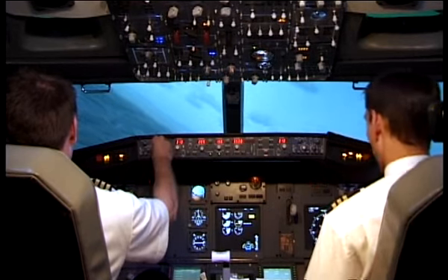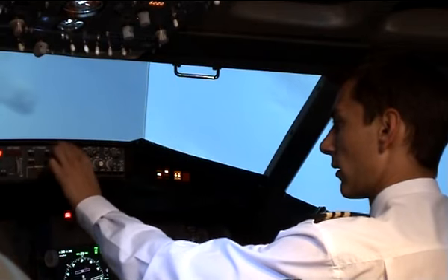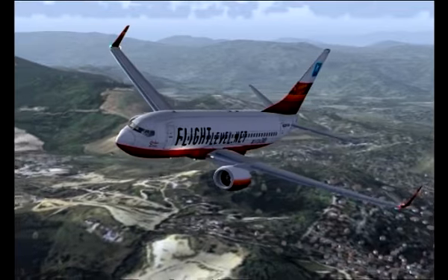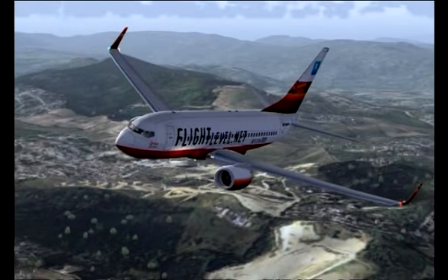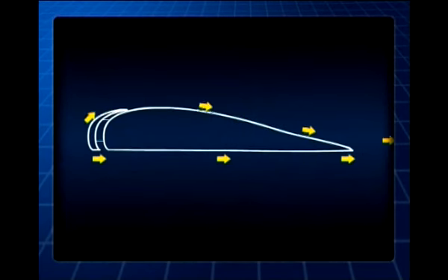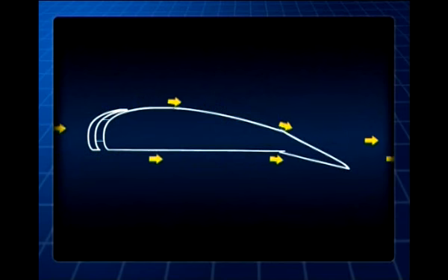Set both sides. With only one engine working, landing must be carried out with flaps 15, instead of the normal setting of 30 or 40 degrees of flaps. The 15-degree position is an ideal compromise between lift and drag.